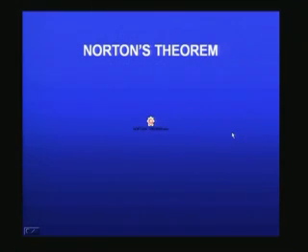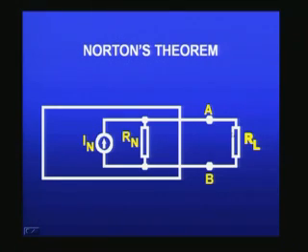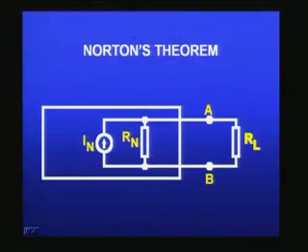So by simulation, we were able to do the Norton's equivalent circuit. This is the final circuit that we have got here. The entire block is removed and replaced by one Norton source and one Norton's resistance, and they are connected in parallel to the RL, the load resistance.